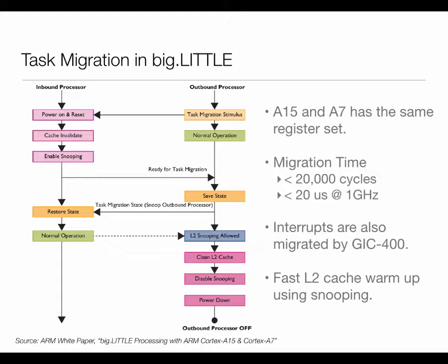You have to decide that there is a reasonable likelihood that you're going to stay put in this new choice, so that this transition cost is amortized. This is still much better than booting up an OS, but nevertheless, when you're looking at processors which are nowadays operating at close to a couple of gigahertz, even in our mobile phones, this is significant.